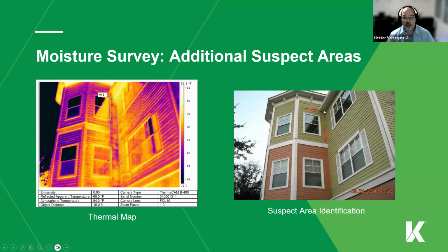Probably it is. So if it's attached, it's leaking into my building, stopping here. This is supposed to be an area where water comes out, probably sealed. Probably you got a crack here as well. So water continues to come inside my panels, which is exactly what we're looking at here. So from an experience point of view, if you hire an engineer or a building evaluator to look at your building, they should have enough knowledge to not only look at the thermal image, but to see the outcome of why that is happening in that particular area.